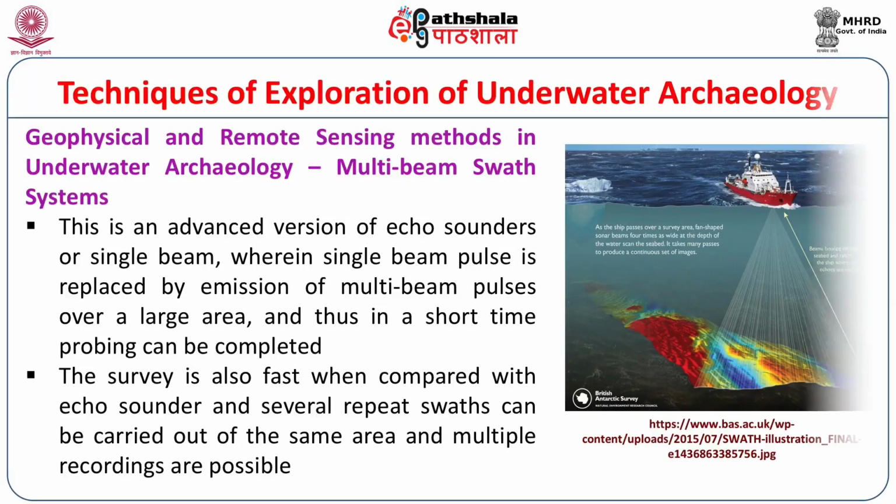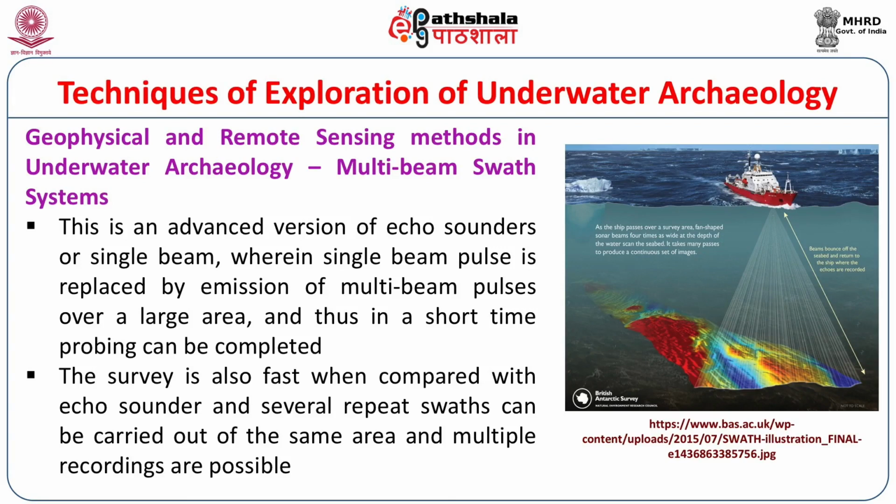The time taken between the emission of the pulses and the reflected ones is measured, which enables us to measure the depth of the water and also the speed of sound in water. So this can be used to understand a relative bottom profile of the buried archaeological feature. If there are ship remains or shipwrecks buried on the seabed, the relative variability of the sound waves reflected from the seabed can be used to understand the buried feature.